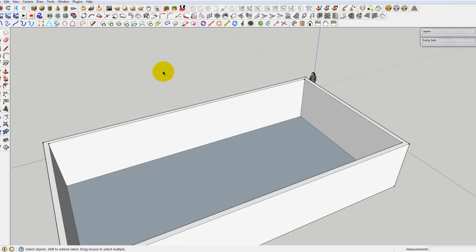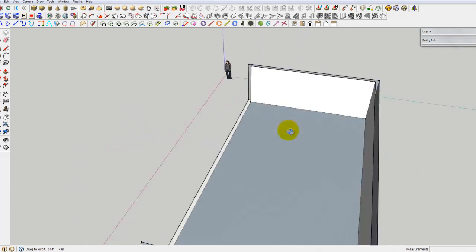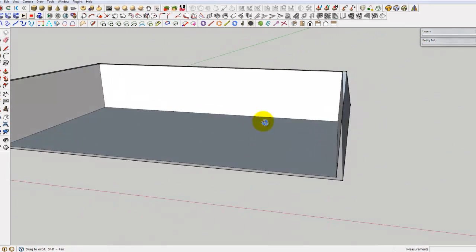Okay, it's something again similar to AutoCAD. I don't know why I keep mentioning that it is always similar to AutoCAD. If you want to select a few things which fall under this window, which actually touch this part of the selection, then you have to drag from the right to the left. Okay, so we're just selecting these objects now, so I'll just delete it.